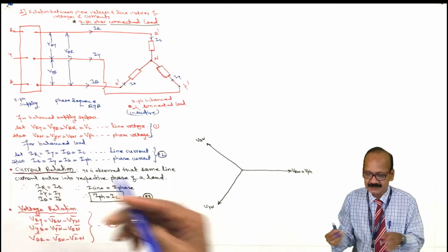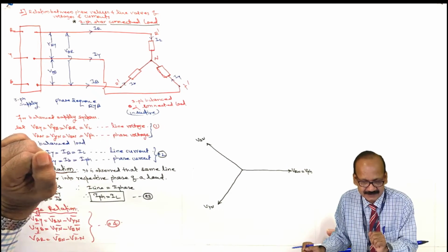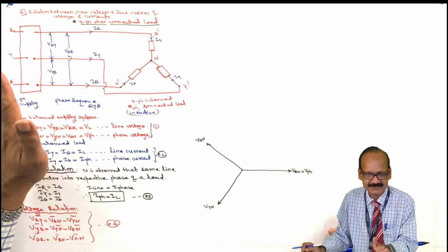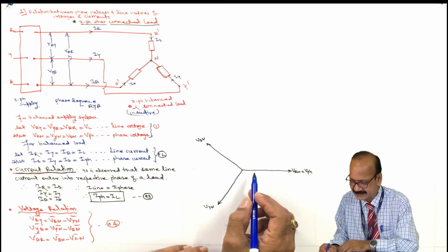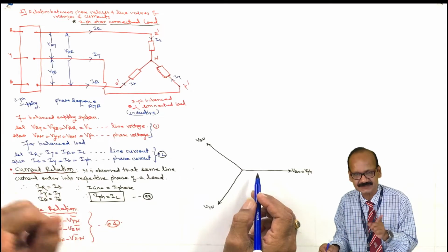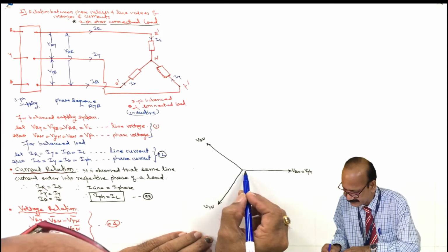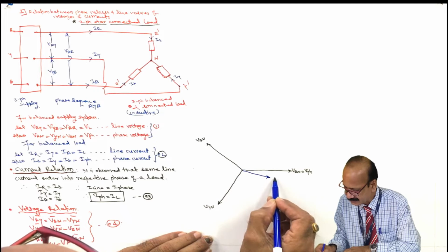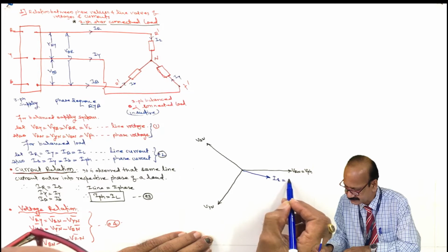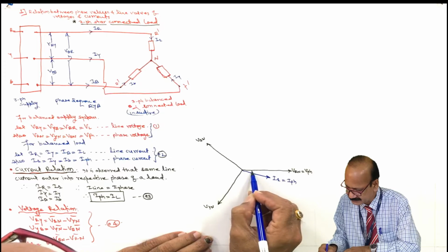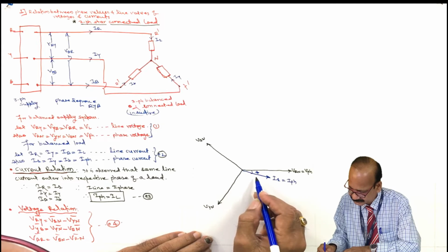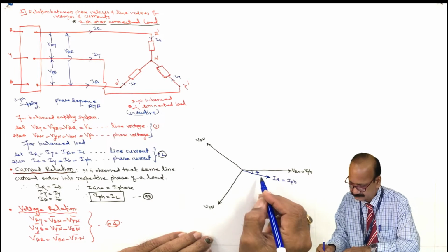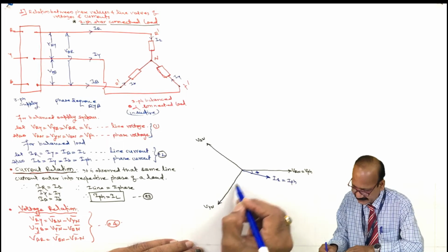Now, as the load is inductive, the respective currents are lagging the voltage by an angle phi. Say, and we have to draw the currents in equal magnitude and displaced from each other by equal angle, that is 120 degrees. Say this is I small r, which is nothing but IPH, and this angle is phi. So equal magnitude. See, this is lagging.